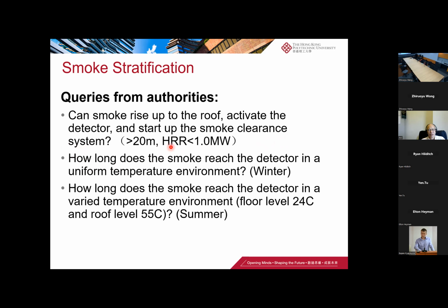And also in Hong Kong Airport, the heat release rate from a fire in the public area or in the circulation area is less than 1 megawatt. So this is the Hong Kong airport terminal requirement. Any furniture or equipment placed in the circulation area needs an assessment to make sure the heat release rate from that piece of furniture will be less than 1 megawatt.